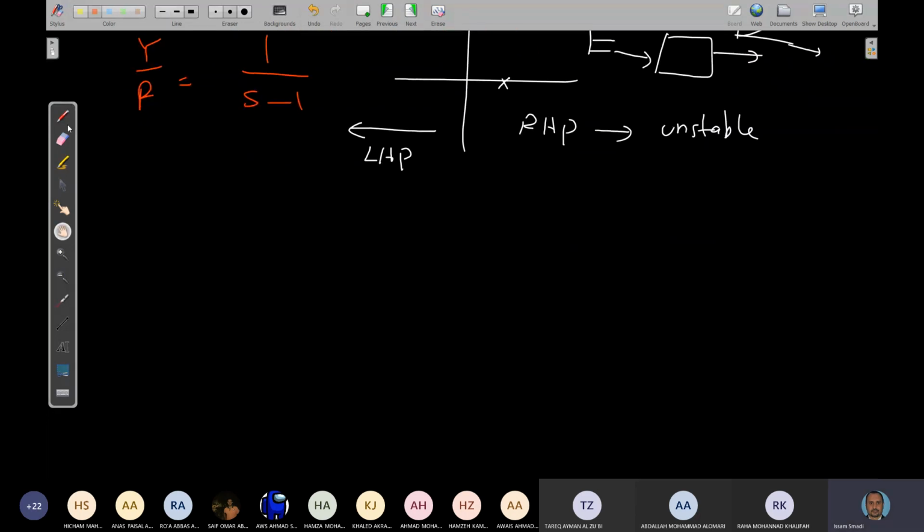Now, from this, if I have the response, let's say y of t equals 3 plus exponential minus 3t sine 5t. Okay. Now this one, stable or unstable? Now simply you say that if the system has a final value, then the system is stable, correct?